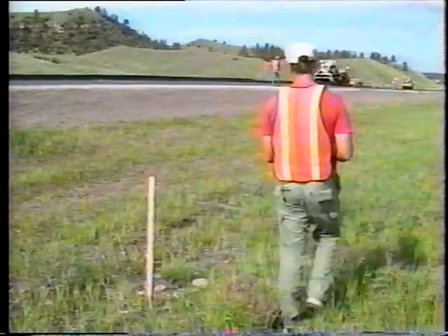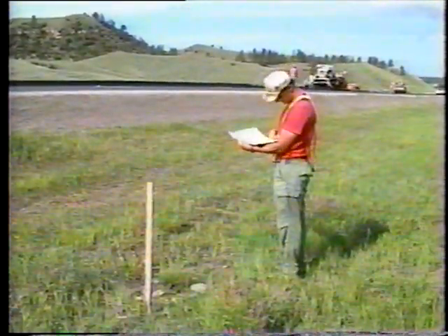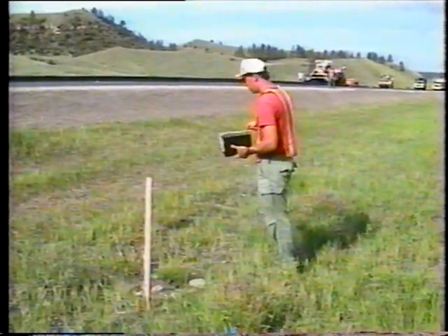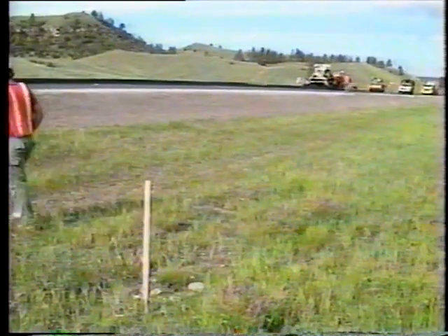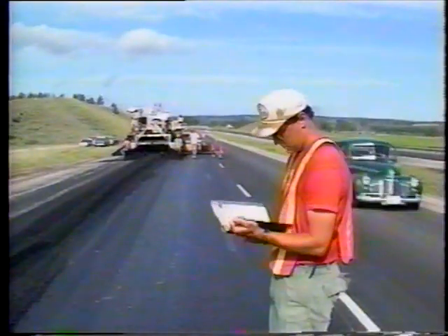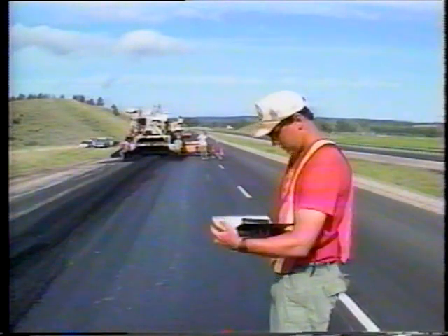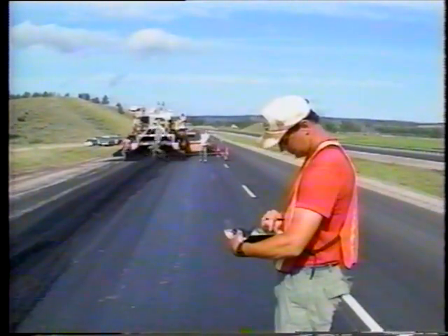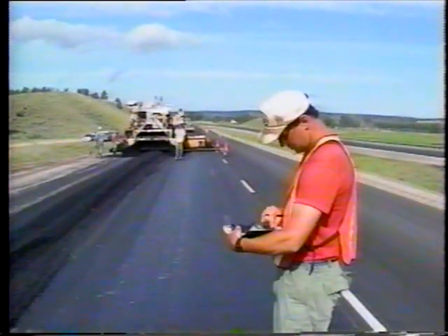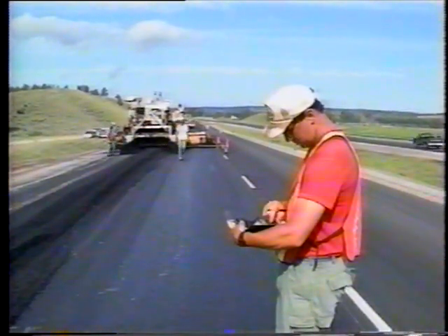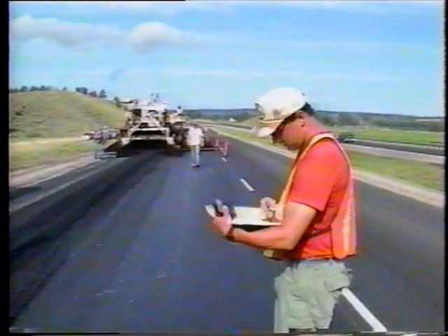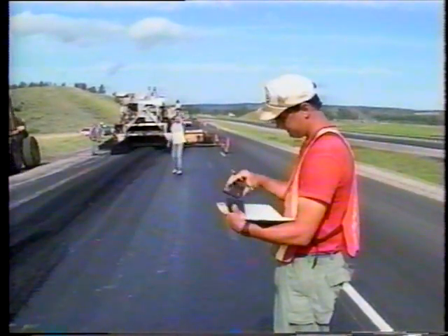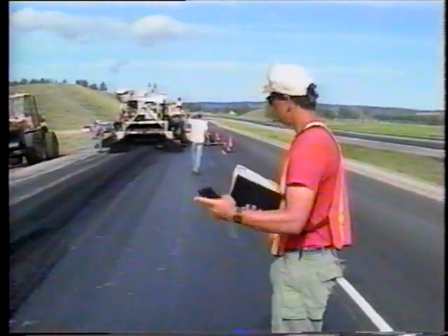Along with your visual inspection, be sure to note the stationing from time to time so you can spot check how much material is being placed throughout the day. You do this by first totaling the weight of mix placed on the road as accumulated from the delivery tickets. Next, you determine the length of roadway paved from the stationing and multiply it by the width paved to get the total area covered. Then, divide the amount of mix placed by the area paved to get the yield. Your checklist has several sample calculations.